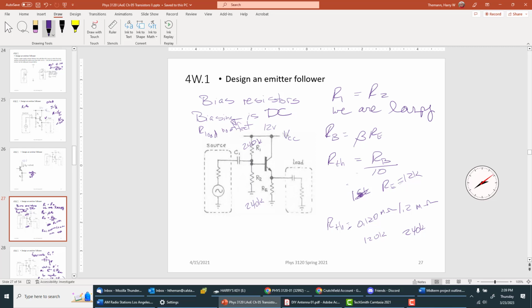We did not have to consider the load resistor because we're going to put the blocking capacitor there. And we also noticed that we haven't even come close to worrying about the 10K output impedance. Everything is much higher than that.